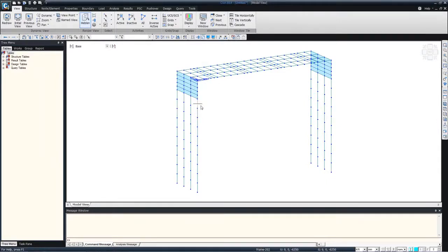So how was this modeled in AutoCAD? I'll just explain to you. All these beam elements which comprise the composite steel girders should be modeled as lines. So nothing should be polyline in AutoCAD. And then you have the piles. Again, they should be lines with all the required intersection points already made in AutoCAD.